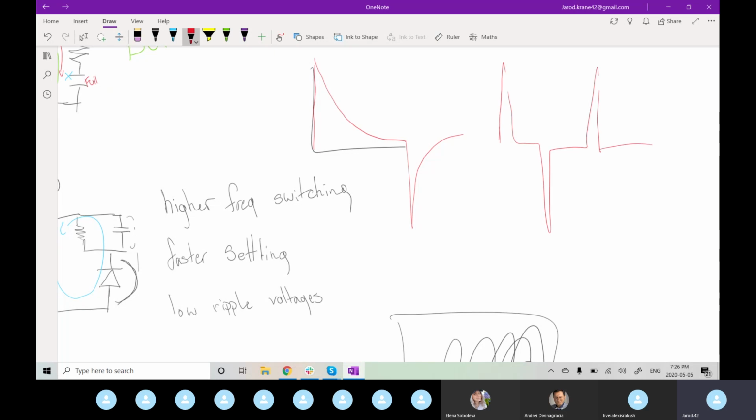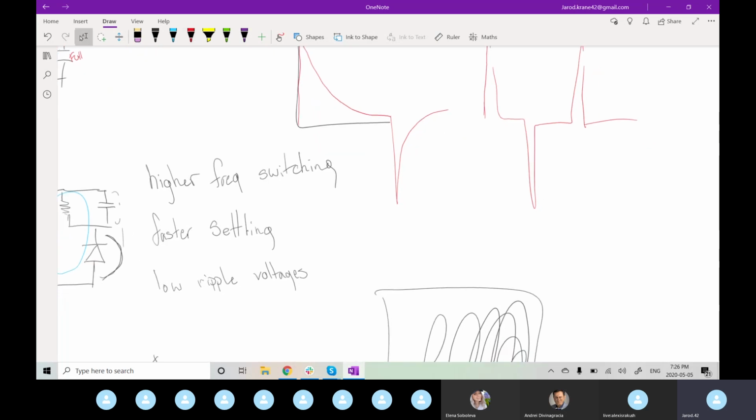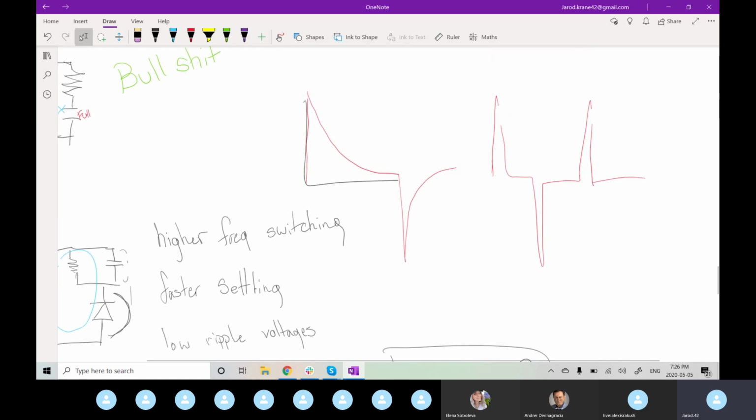It may not be that drastic, but since you add the capacitor into your system, which acts oppositely and doesn't like changes in voltage, it reduces these spikes, so you get safer, more tolerable voltage spikes.